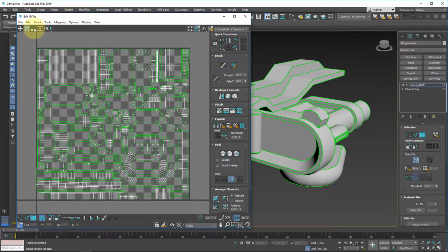Of course, the next tool is your Scale tool. So if we click on this and select our object, we can scale it universally. If we want to restrict our scaling onto one axis, hold down Shift and you can scale it either sideways or up and down. Of course, we can do the same thing once again by holding down our mouse up here and choosing the axis we want to restrict it on. Next is the freeform mode, which lets us pretty much scale, move, and rotate in any direction we want, all without having to keep selecting a new transform tool.